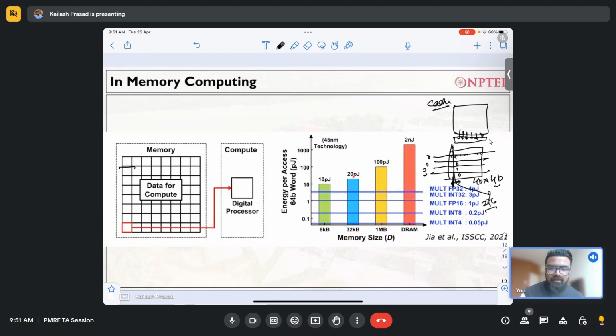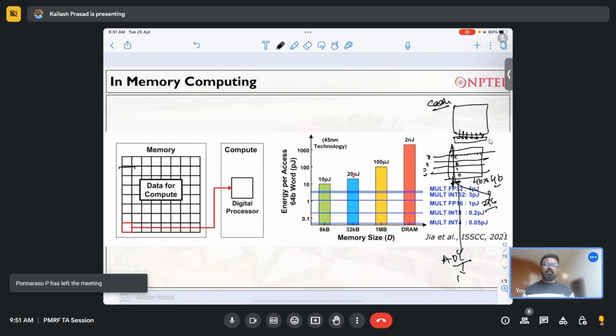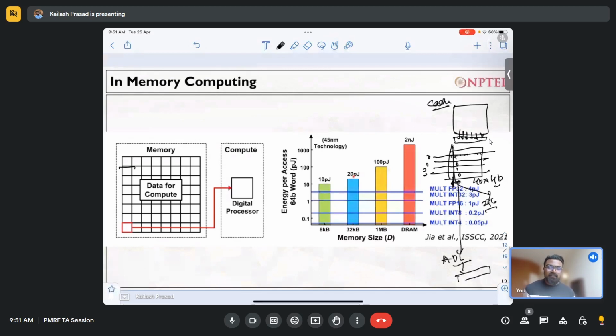Digital nature isn't digital nature. It understands everything binary. So if you want to know what the computation is, whatever the final output is, you put an analog to digital converter, ADC, over here, and you will get a final digital output of a 4 bit cross 4 bit multiplication. And this is not only being done in SRAMs, we are doing it in DRAMs, flash memory, the hard disk, everywhere.